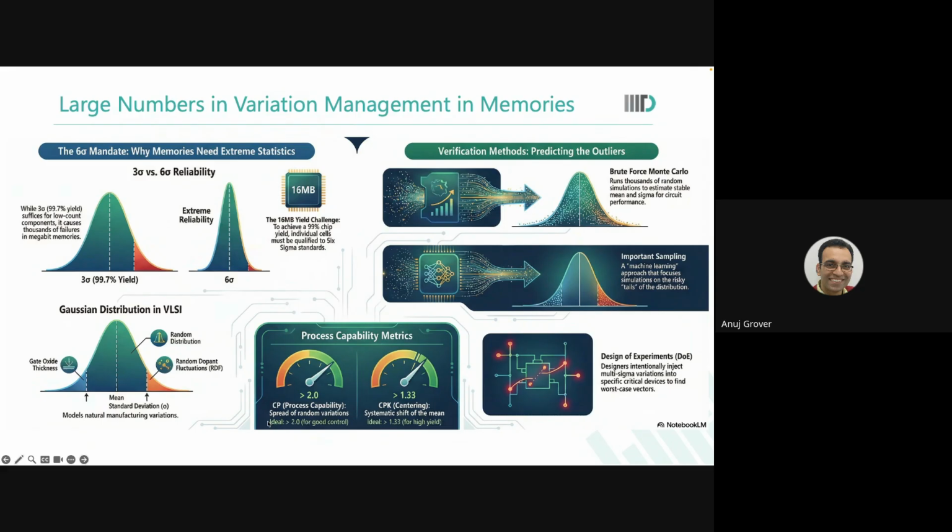The plus minus 3 sigma qualification is the way analog circuits need to be defined or handled. The sheer numbers and the statistics indicate that those methods would fail if applied to memory design. So verification in memories has to be done very carefully, very judiciously, taking much larger variation extents into consideration than designs elsewhere. Are you with me?